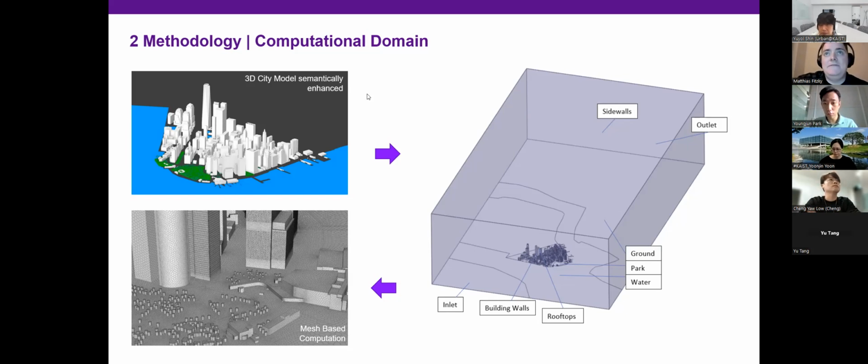So I can definitely improve this current procedure. What you would have to do is go into this 3D city model and incorporate this newly planned building, or you can also completely exchange the whole model which you are simulating. Then you can assess how a planned new city district would behave thermally, and where there are corridors where ventilation isn't happening, for example. That can then be improved, and the overall thermal comfort for the newly planned area is also taken into consideration and can be changed according to the needs. So that works. As mentioned, you can run through certain scenarios.